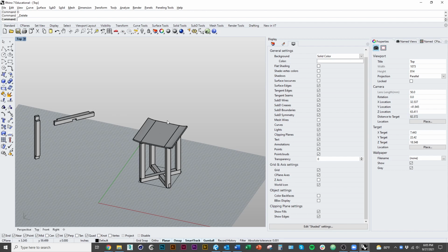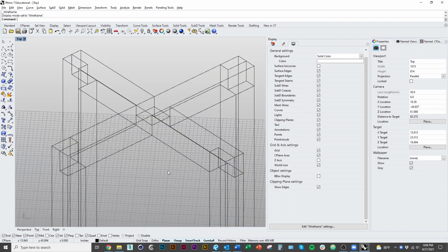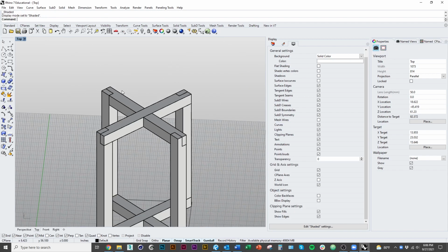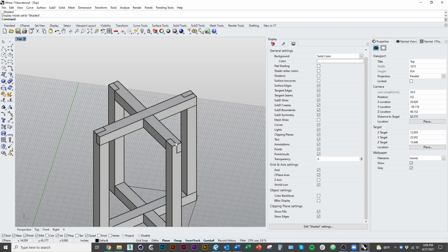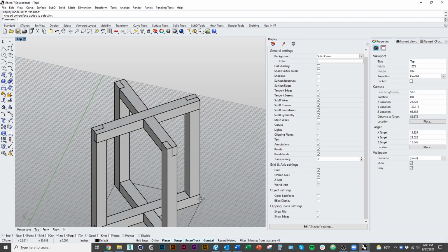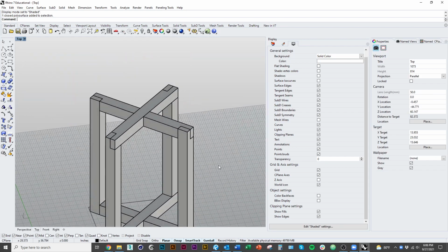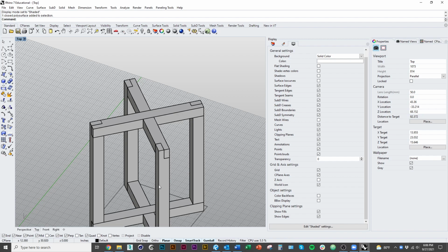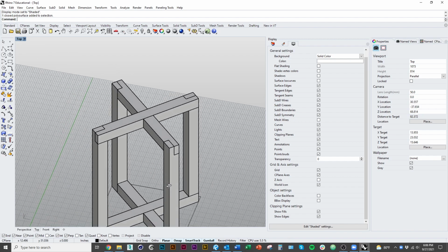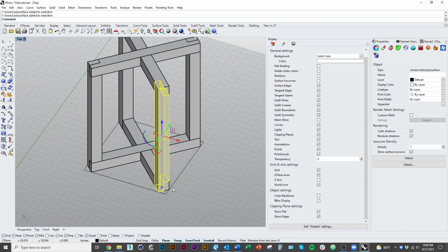Now, I wanted to point out one other thing that I didn't mention in the previous video, which is that we can also adjust. So the main technique that I talked about for modeling the joints was to use Boolean subtractions to carve out the pieces where they would intersect, so we can essentially model what the real joints would be like. Now let's imagine that we are modeling it, but we're learning about the design and we're needing to change things as we go. It doesn't mean that you have to completely redo this member.